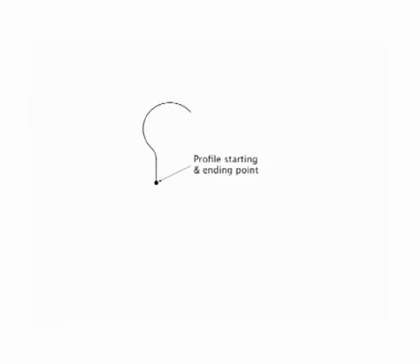For our demo, we will start the profile at the left side center edge and then program our points in a clockwise direction around the profile until completing the shape. The process of programming our part in the Fagor profile editor will follow this sequence of steps as an example.